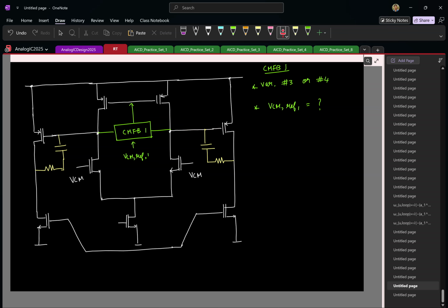Now remember, for a differential mode operation, you would have designed the second stage to have some gm. And from the lookup table, you would have found that I need some particular VGS for this. Correct? So let us say you already designed this so that it carries some particular current, say I6 or something. I'll call this M5, M6.